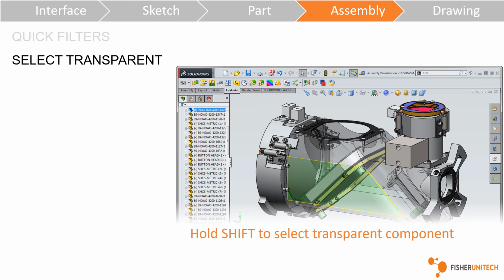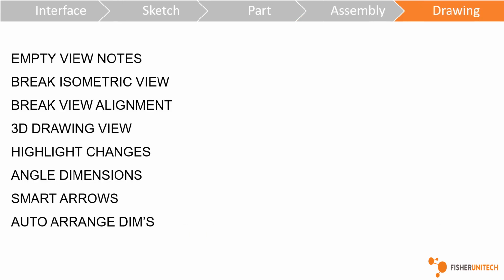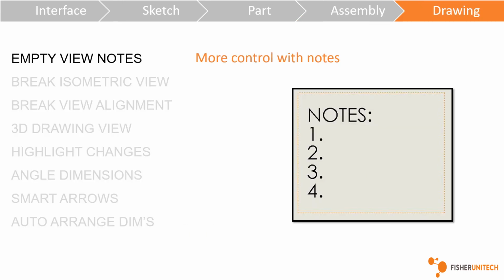If you ever make faces transparent and you still need to select them, which happens pretty often, just hold down Shift and then you can select that transparent face. So again, something very quick, very simple, that can be helpful if you're trying to select that face. Alrighty.